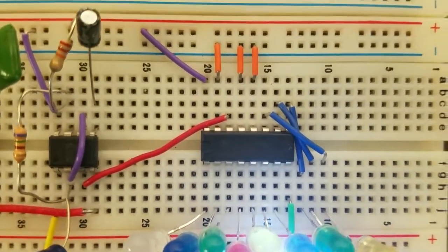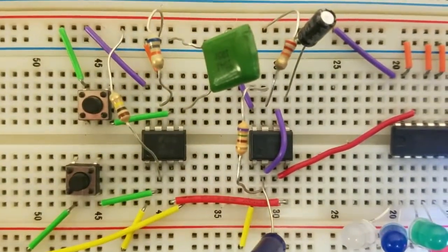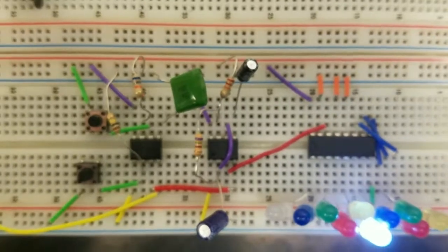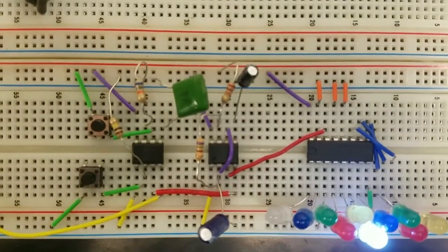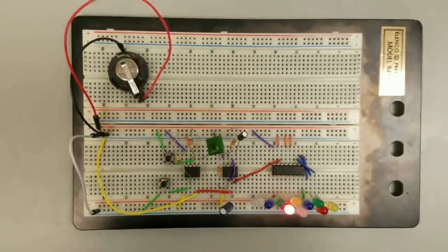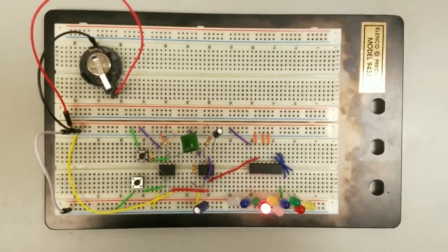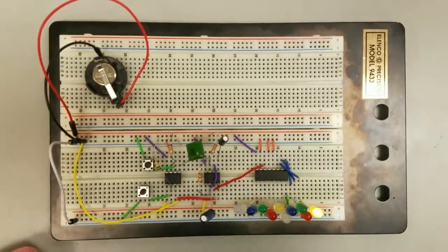Now let's talk about the RC timing circuit in the astable mode. The values we chose, 750 ohms and 10 microfarads, set the period to 0.16 seconds, which means that every 0.16 seconds, the lit LED will change and go to the next output on the decade counter. This was chosen since the average human reaction time is 0.25 seconds, which presents an above-average challenge for the players.